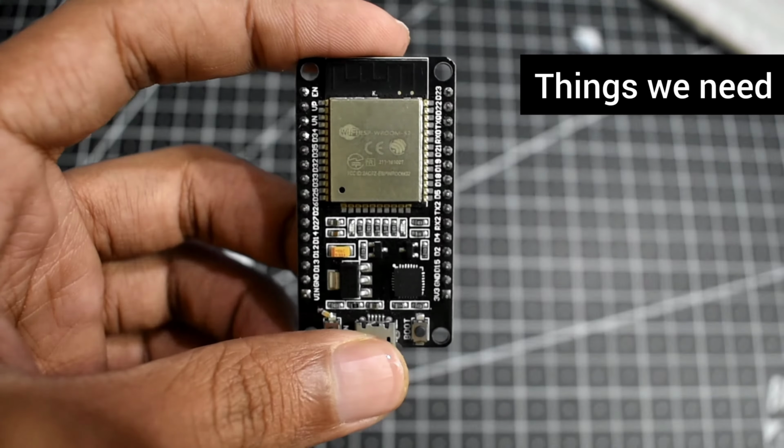The same way we will write humidity equal to DHT sensor dot read humidity. So now these two functions are done. Now this variable is a float type, so I enter float there. Both of them are float values, otherwise we will have an error saying undefined data type.